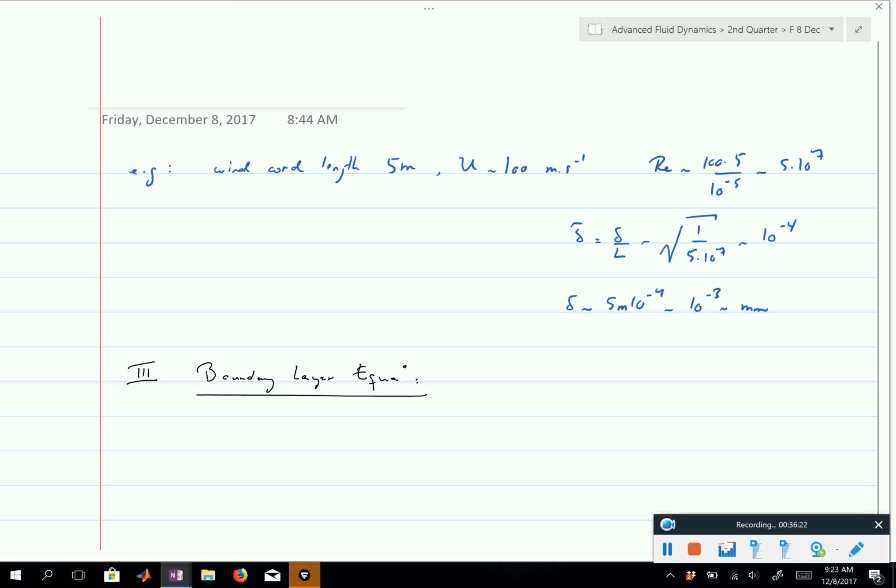In that boundary layer region, the length scale in the x direction could be anything. It goes from 0 to L, the length scale of the plate. But the length scale in the y direction is roughly delta. When we assume that, the equations simplify to a certain extent, which allows you to solve them, numerically, but it still simplifies them. So it's not a different equation, it's not a Stokes equation. You could retain all of the terms you wanted, but they become very complicated to solve. So we'll just rewrite the Navier-Stokes equation and put ourselves in that small layer.